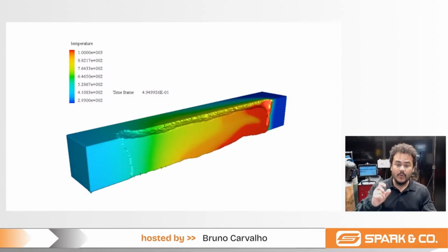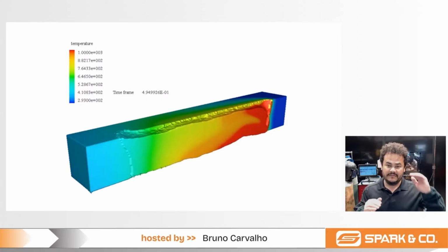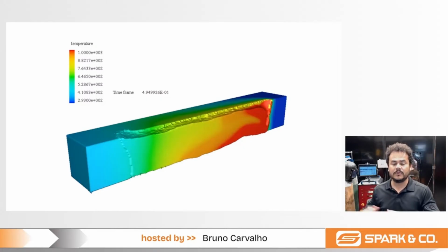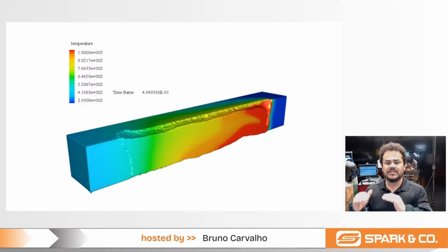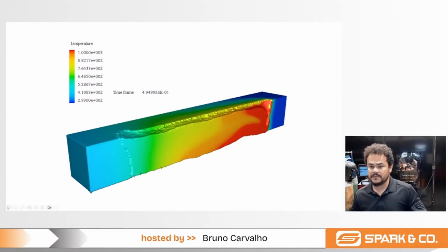So again, if we want a deeper penetration, we need to adjust the traveling speed. If we don't adjust the traveling speed, we may have this problem. We have the penetration, but then we also have porosity, or gas entrapment in the material. We need to adapt both, right? So if I want more penetration, let's say I want 8 millimeters deep with the LightWeld 2000, I need to adjust the traveling speed or the laser frequency to avoid having porosity inside my weld.